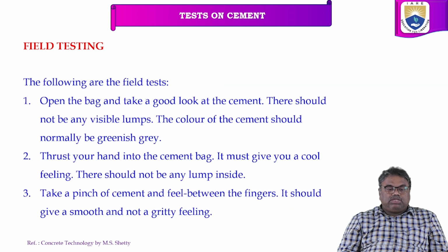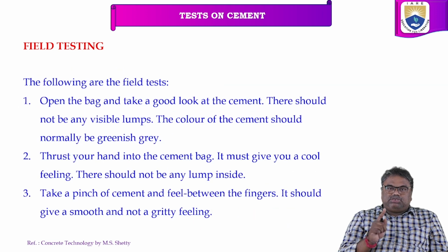Once again, the first one is to open the bag and see whether it has a good look, and the color should be greenish gray. The second one: thrust your hand into the cement bag, and you should feel a cool feeling inside the bag, and see that there are no lumps inside. Take a pinch of cement between the fingers, and you have to get a very smooth feeling.